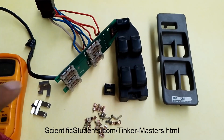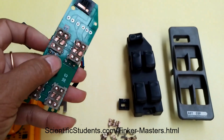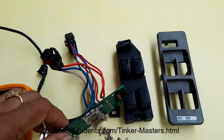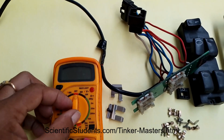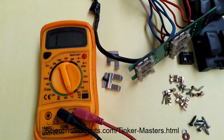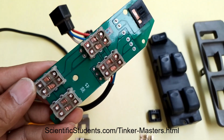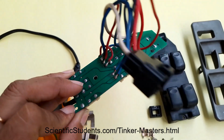To understand this logic, how the switch connections are happening and how the motor connections are going on, I have used a digital multimeter in buzzer mode. I have seen the continuity of the tracks, what is connecting where, how the PCB is designed.